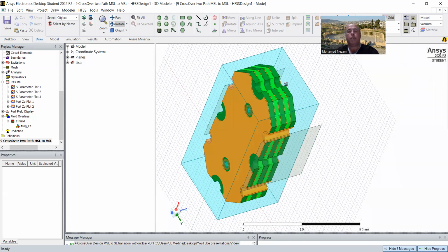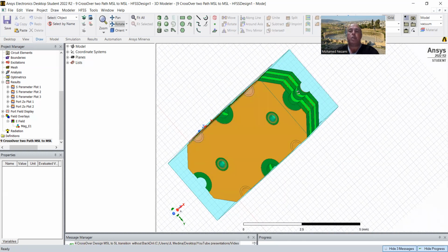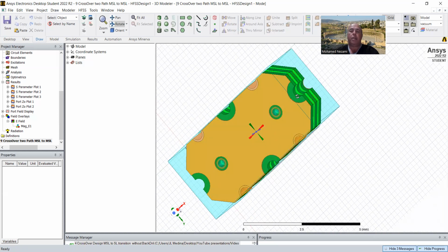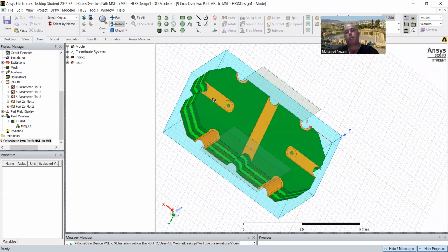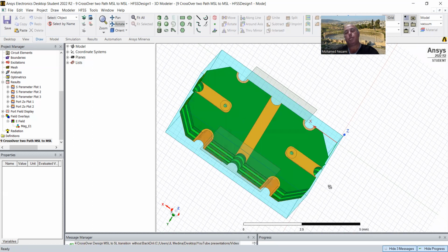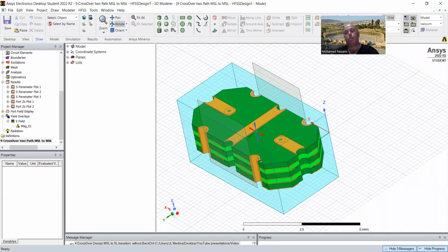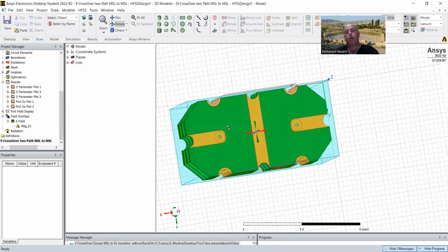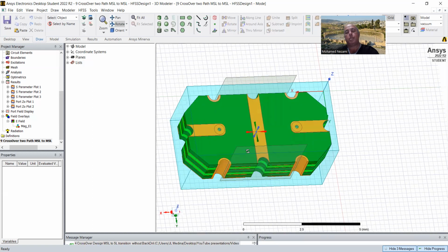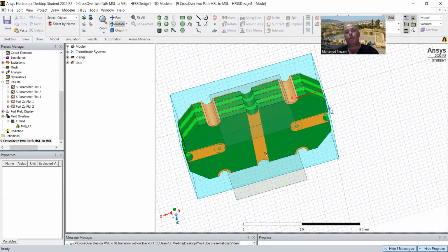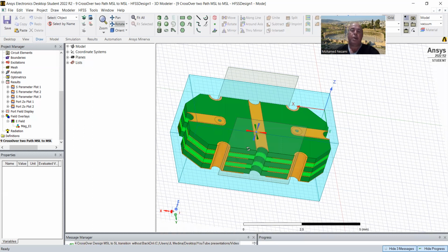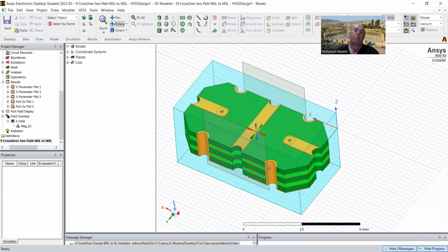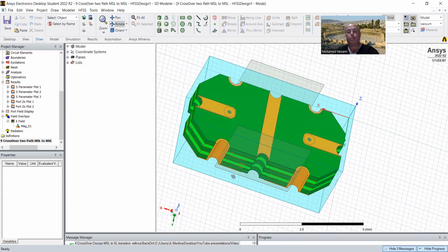Okay, we're going to make a little, this is edge plated in here, a half via on the side that will serve as an input port to one of the signals. Same thing in here, and we're going to do the same thing to the other one. And then I'm going to use these as ground vias. Okay, so these are the ground vias. There's 4 of them. Okay, and so tune in to the next video, and we will go through this from the start and see how this will do.